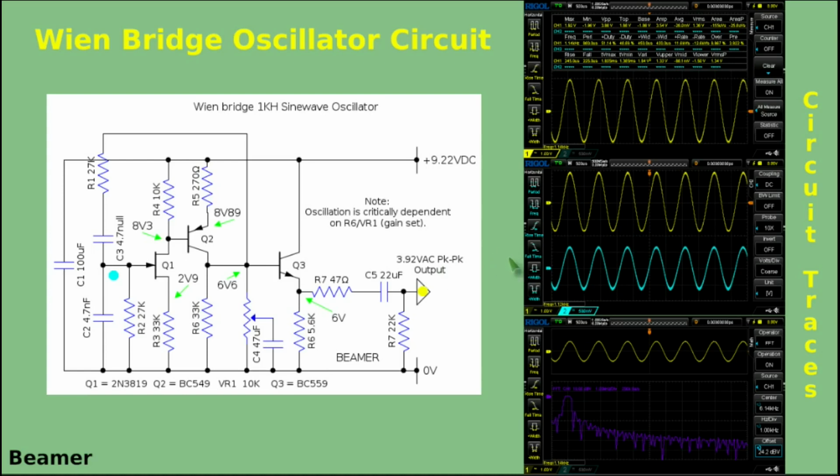And bearing in mind that this is continuous oscillation, so it would have to be very slightly higher than the absolute minimum. Secondly, you can see that the phase between the output here and the input is 360 degrees, or in fact 0. The peak here on the blue lines up with the peak on the yellow.